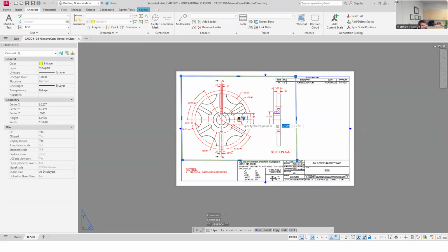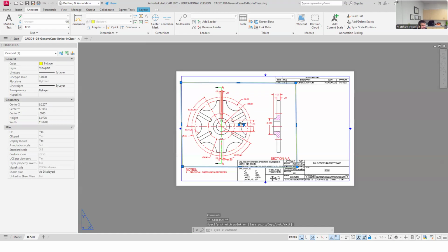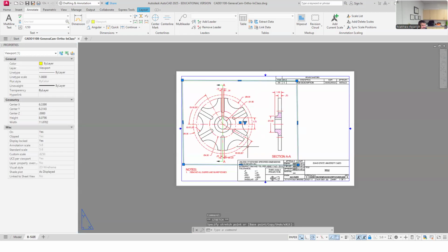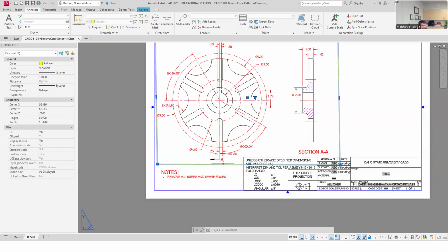What I think about a little bit when I start titling views like this is that I do like those to be as low as the lowest point. I'm not going to be able to do that here, and it's not the end of the world. But if I have space, and these are orthographically aligned, sometimes my headings will come down and be at the lowest point of the data. Just for my own cleanup, I like my headings to line up with the lowest point, so I don't have this jog, but it's okay here.